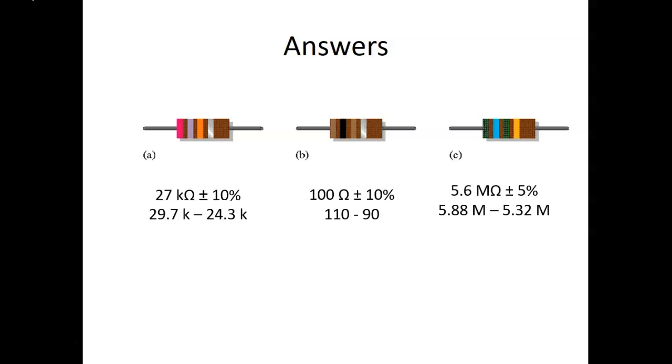If you cut too long, in other words, if you cut something like 30 kiloohms, that's too big. That is outside the range you need it. If you cut too short, let's say you cut 23 kiloohms, that means that you're going to be outside your tolerance and whatever you're building will not work. Correct?